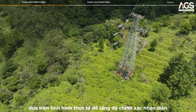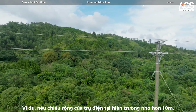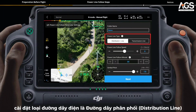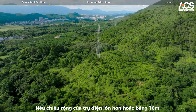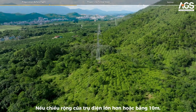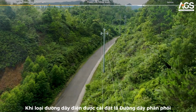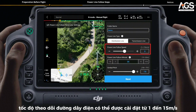To increase the identification accuracy, for example, if the width of the on-site tower is less than 10 meters, set power line type to distribution line. If the width of the on-site tower is greater than or equal to 10 meters, set power line type to transmission line. When power line type is set to distribution line, power line follow speed can be set to 1 to 15 meters per second.